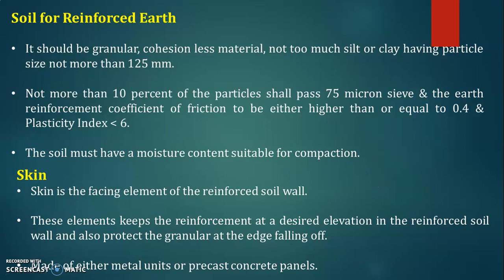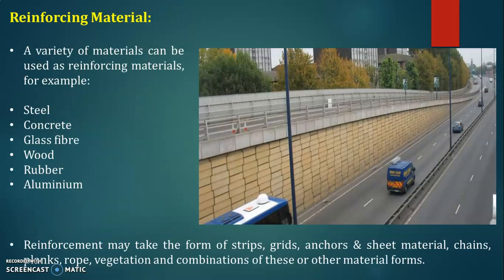Skin is the facing element of the reinforced soil wall. These elements keep the reinforcement at a desired elevation in the reinforced soil wall and also protect the granular fill at the edge from falling off. Made of either metal units or precast concrete panels.